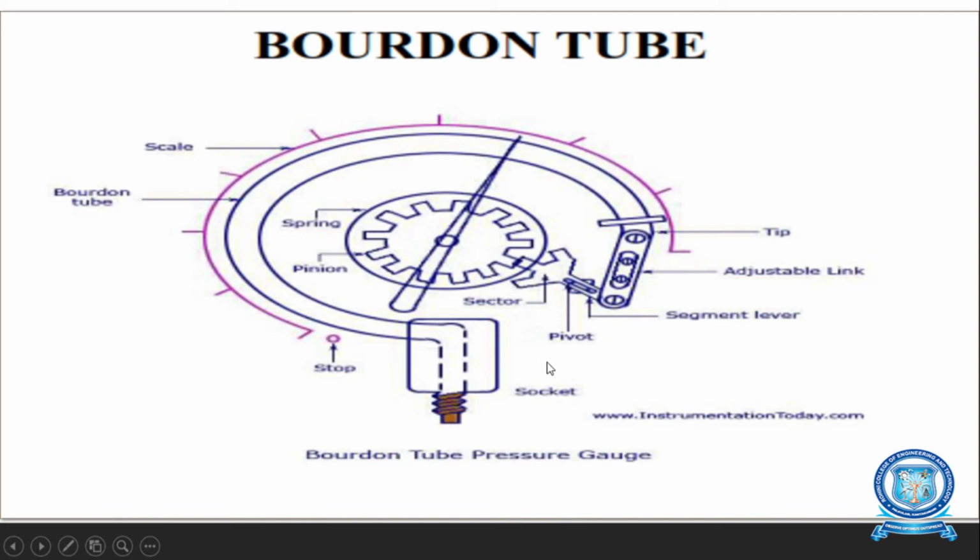In this Bourdon tube pressure gauge, it is the simplest tube which will expand when it is exposed to pressure. This expansion is the measure of pressure. One end, called the tip of the tube, is sealed, and it is also called the free end. It is attached by a light link work to a mechanism which operates the pointer.